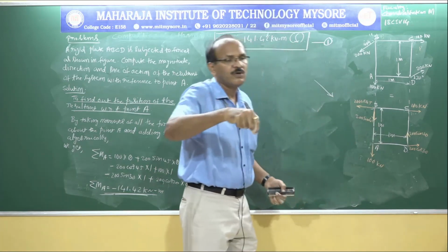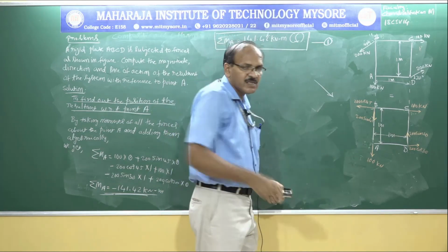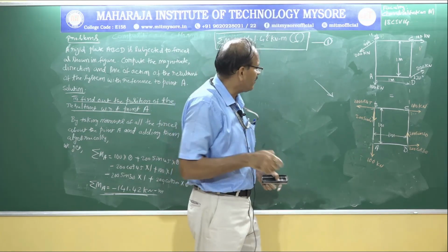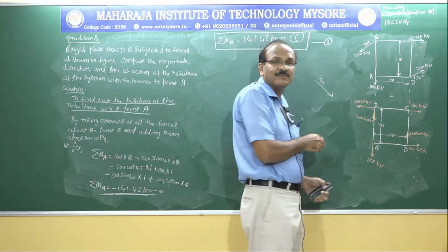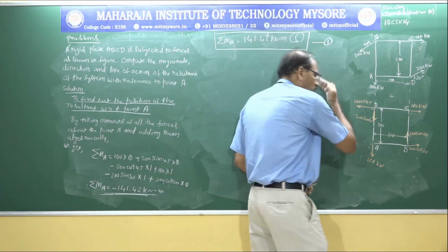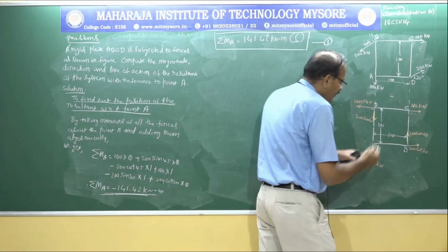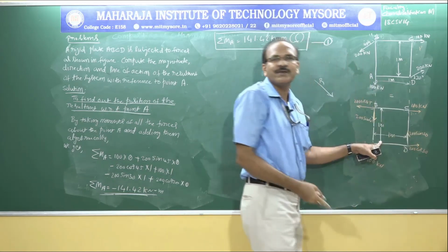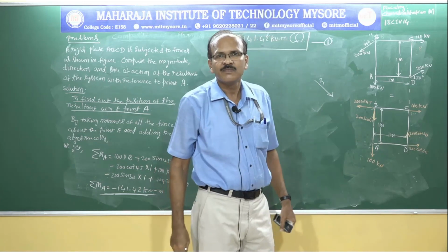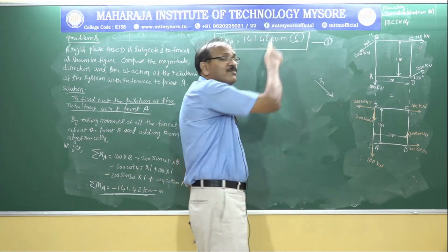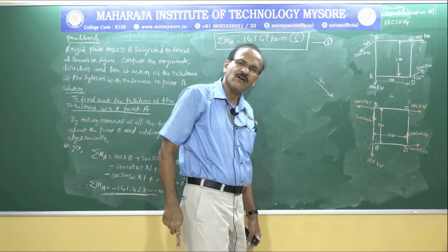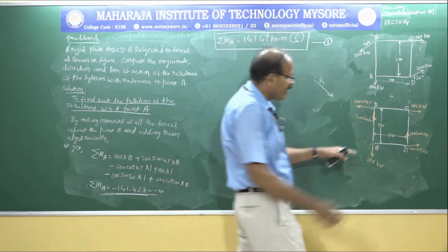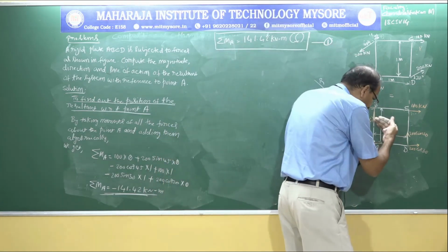If you look back at the previous figure which I wiped out just now, if I move this resultant on this side and take the moment of the resultant about point A, that causes clockwise moment. Okay, but what is the resulting moment? Anti-clockwise. So we cannot place that resultant on this side.